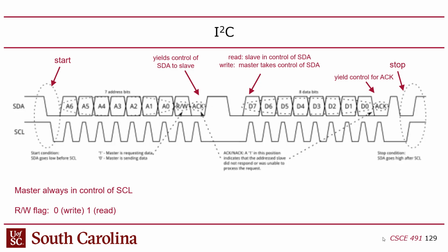I don't know if it's actually required that data goes down, then clock goes down. Yes, that is required. Data goes down, then clock goes down, because you got to bring clock down to prepare it to pulse, right? So data goes down. Data change when clock is high. That gets everyone's attention. Then we have to drop the clock, obviously, because we got to get clock down in order to go back up to sample, right? So data down, clock down. That's the start.